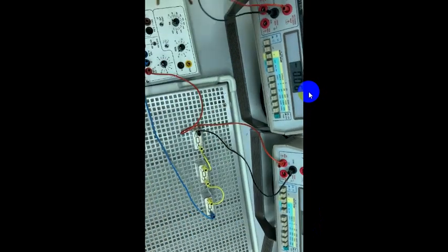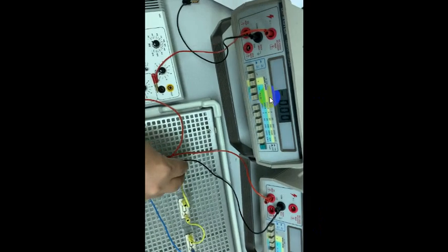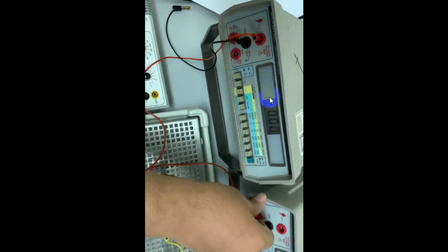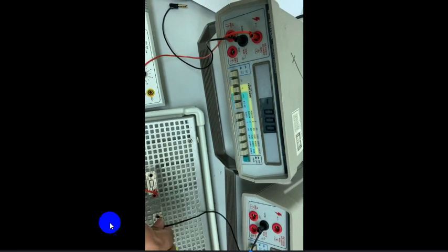So now what we are going to do is connect the second ammeter in between R1 and R2. I have to remove these two. You can see I removed these two series connections and put the ammeter in between, and I will see what is the change in the current. Here it was how much? 12 point something. So is there any change when it is connected in series? Let us verify.